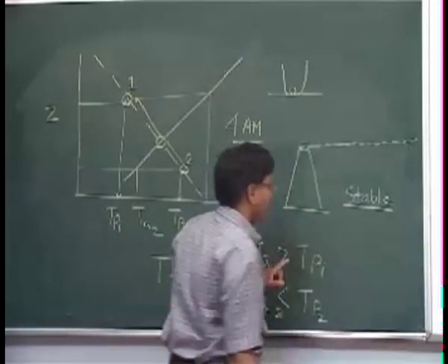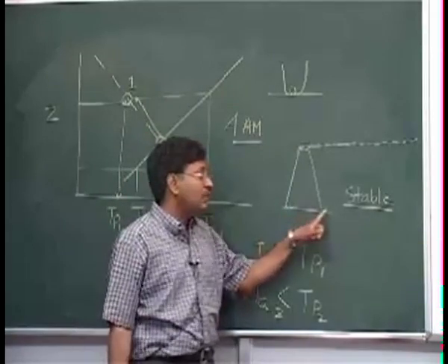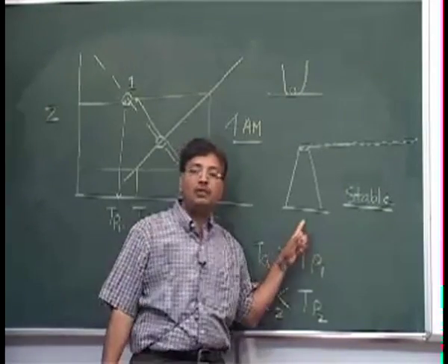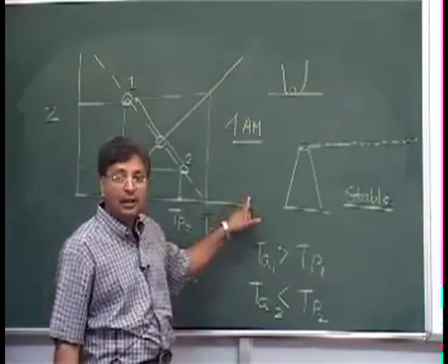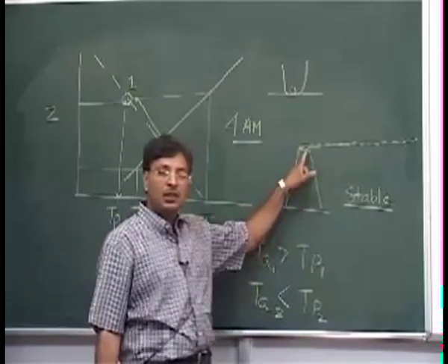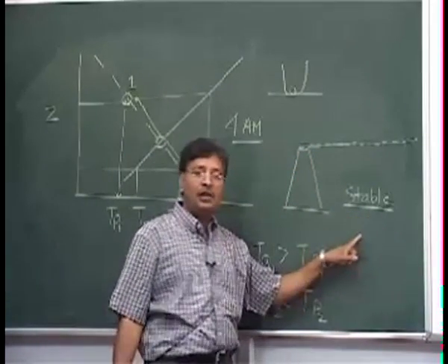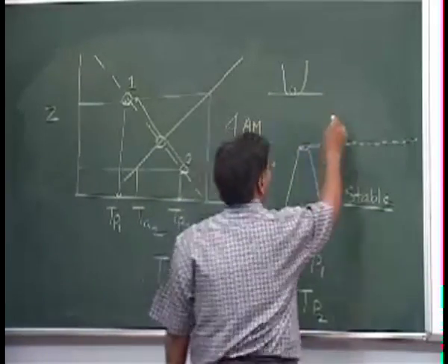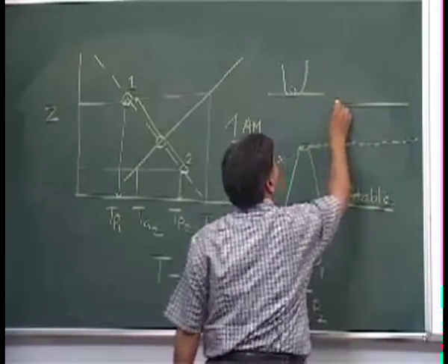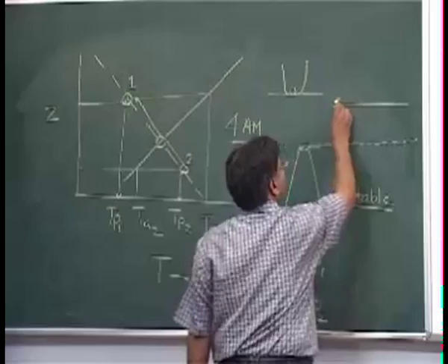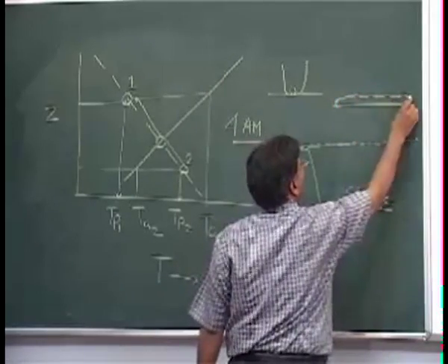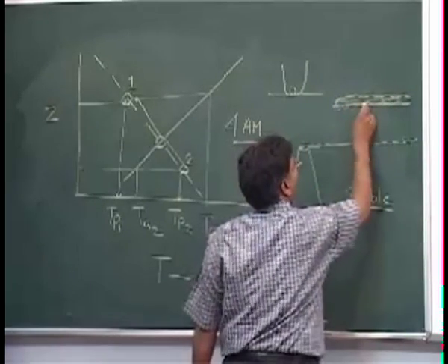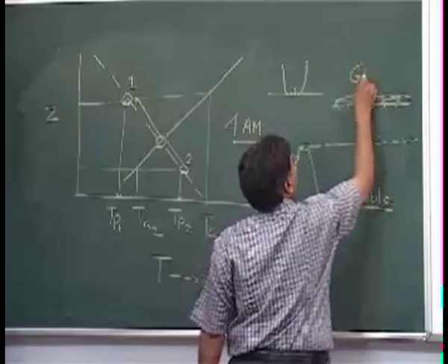But you see the advantage here is that the people at the ground level are not so much affected. So in a way you are saying stable conditions are bad, but if the source is an elevated source, the problem faced by the people is not so bad. But just imagine if the source was a ground level source. You see, this will not disperse. As a result, the entire population will be affected. This is the ground level source.